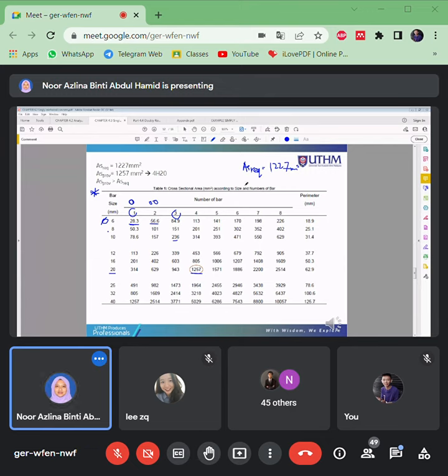So the reinforcement that you will provide, we call it AS provided. This is what you provide according to the AS that is required. So AS provided here should be equal to or more than it. It cannot be less than AS required, even by 1 mm.